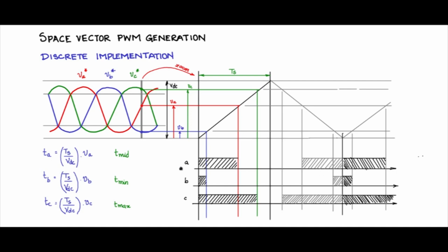So this way we can implement the space vector PWM. This in fact would be the analog implementation. Just compare and then pass it through a comparator. But in the digital domain, we need to give values, numbers to a compare register, and it will compare with this counter or timer and then make a port high or low depending upon the compare value. So how to calculate and give? We have calculated TA, TB, TC. But observe that,